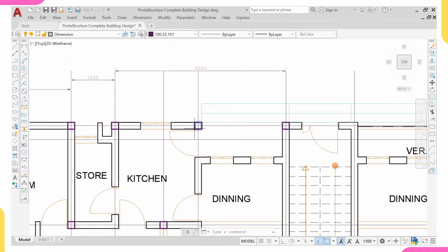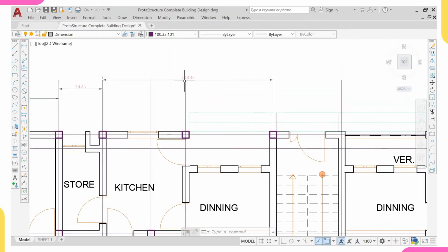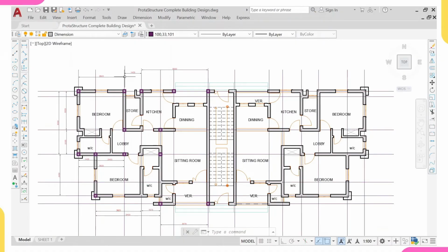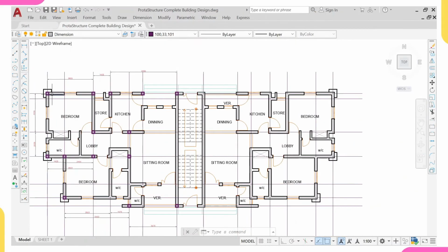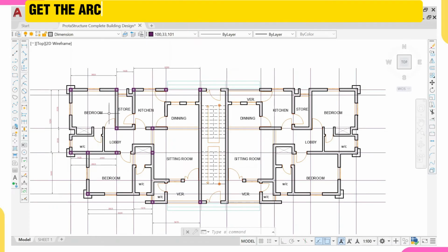You are still economical in your design because the cost of this column now, this is 4y16 and a concrete. But if you remove it and just replace it with just one bar of y16 of 5.5 meter length, that means you save cost. But the client doesn't know because all the work they have done is that maybe they will have columns placed here, here, and here. They'll have columns placed all around the building. Then they'll think it's normal, but they don't know. And two, the more you are placing columns, the more you are having 2y16, 2y16. That's what they don't know, but you have to educate them so that they will know.